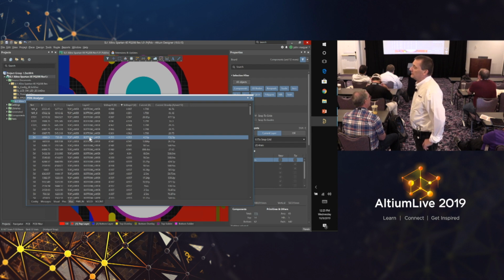So if I have a location that's really high current density, if I put a maximum, hey, this needs to be 10 degrees C above my simulation temperature, which say is, I don't know, say it's 100. Right. So say I can only get to 110. And I want to say, hey, this spot's going to exceed that based on copper thickness and thermal properties of the materials in the stack up. So I don't know if anything like that is planned, but we can take that.